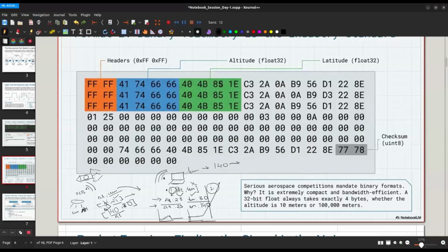And it is not a problem of synchronization. The baud rate, the rate of transmission of data that both could understand, was fixed. It was 9600, so it was the same. It is not the problem of the baud rate. The communication of your laptop to the Zigbee was with the UART, so that is the same as well. So there is no problem in receiving from the Zigbee or the USB.